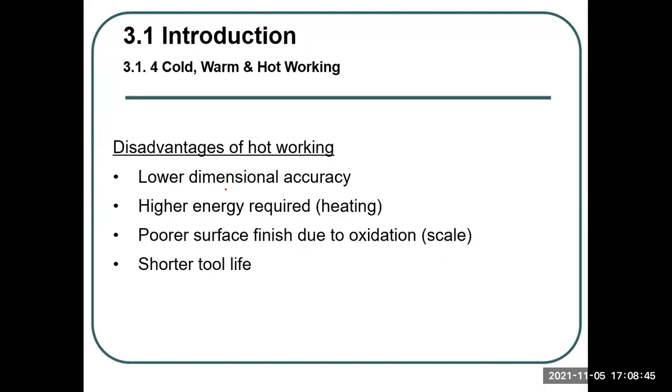The disadvantages: because you need to cool down, there will be shrinkage, so it's more difficult to control dimensions. There is higher energy because you need to heat up, and poor surface finish because you might have a lot of oxidation, which makes scales. The tool life might also be shortened because of the heat.